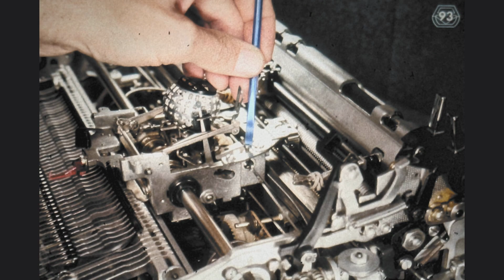Now we can reinstall both tapes onto the anchor screw in their proper order. The tilt tape goes on top and the rotate tape goes on the bottom. It is very important to make sure there is no twist or kink in the tape from mishandling during removal or reassembly. A sharp bend will require tape replacement. Once both tapes have been fastened onto their anchor screw, we must again carefully release the rotate spring tension.